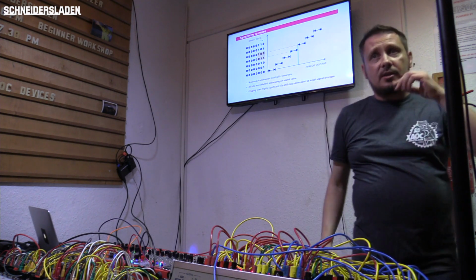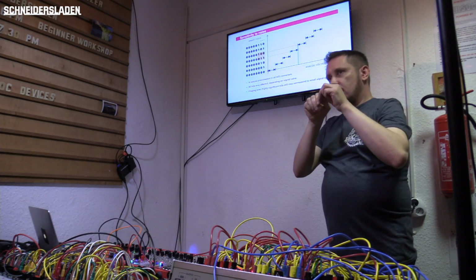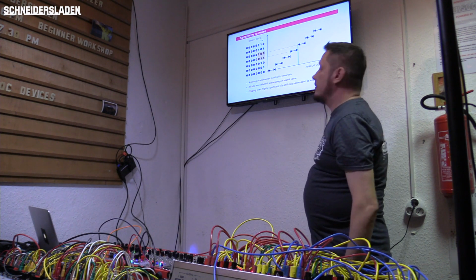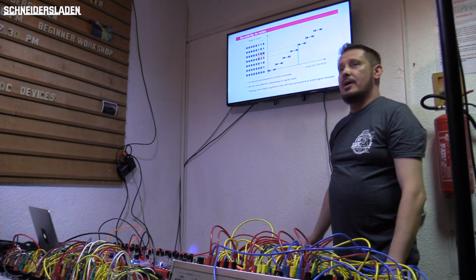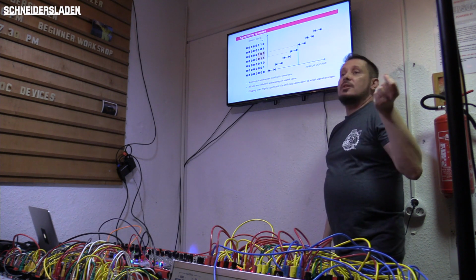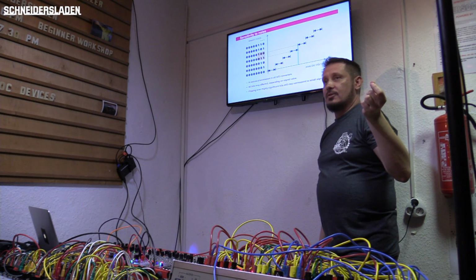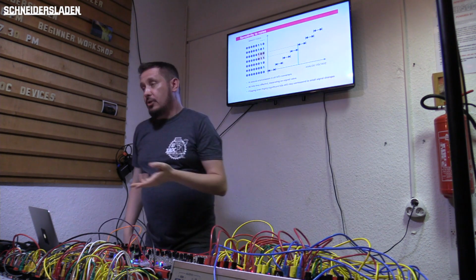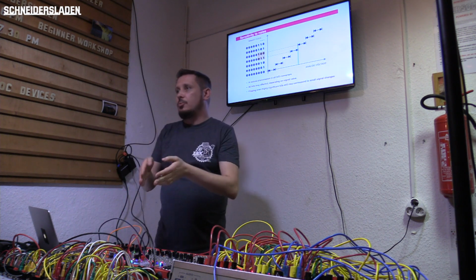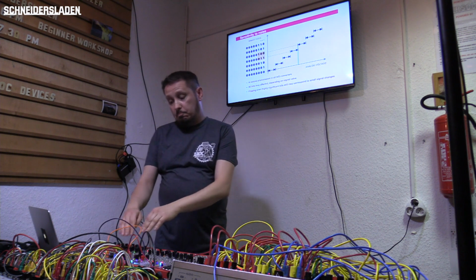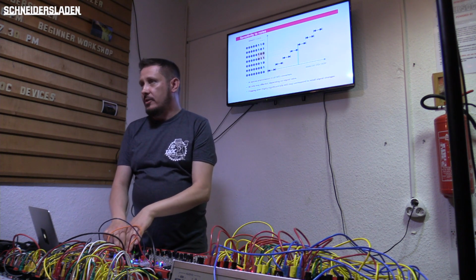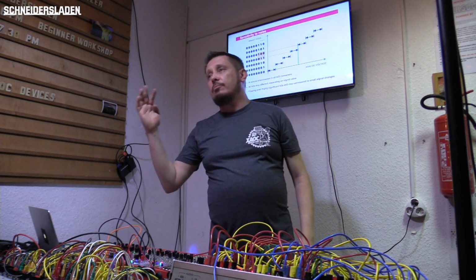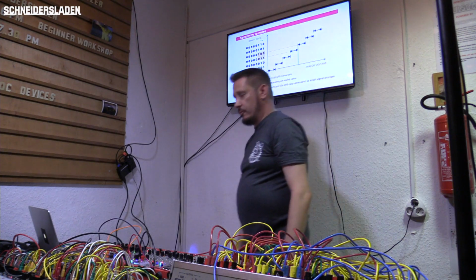And if you recall that at the middle of the range there is all ones and 0 at the highest position, and the next step is 1 and zeros, also the most significant bit can flip due to the presence of noise. So it is actually very important to use a clock to stabilize the output of the converter if you want to have stable gate signals at these binary outputs, if you want to use them for rhythmic purposes, for clocking devices and so on, the sequencing.